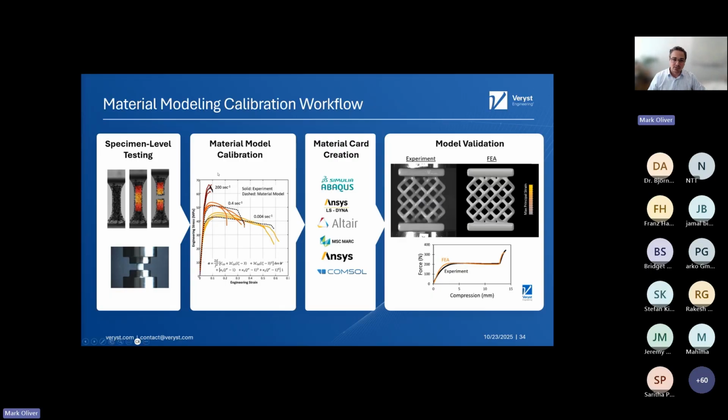So we're treating the adhesive or the polymer, so you can cast or cut out tensile specimens of the adhesive, or you can test the material using the standard compression test. Then once you have that raw stress strain data, you can calibrate constitutive models that can capture whatever it is that you're trying to describe: the yield strength, the rate dependence, change in stiffness, etc.